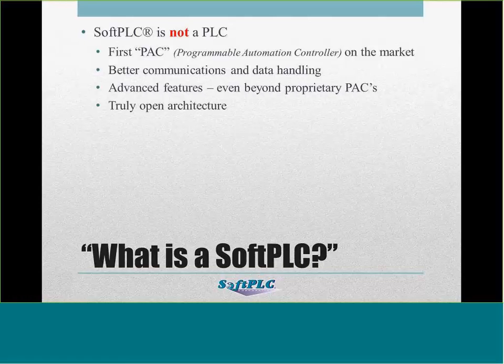They're relay replacers. They're great for small machines, but when you want to do something fancy, you want a Programmable Automation Controller. Soft PLC is a Programmable Automation Controller, which means it has better communications, data handling, and advanced functions that you don't find in a traditional PLC.